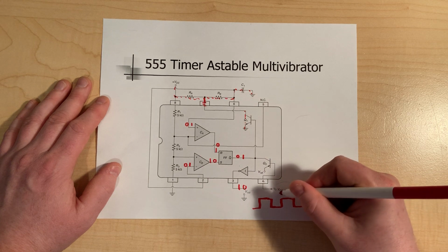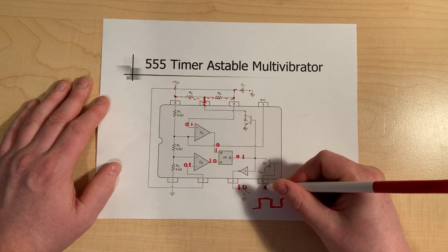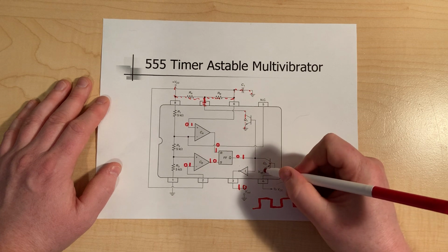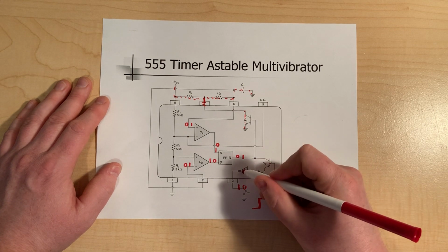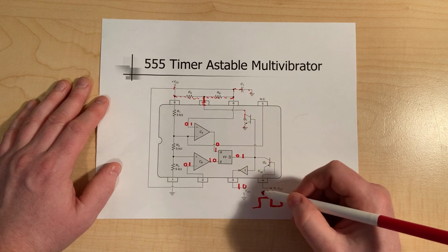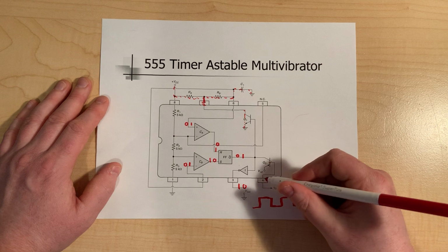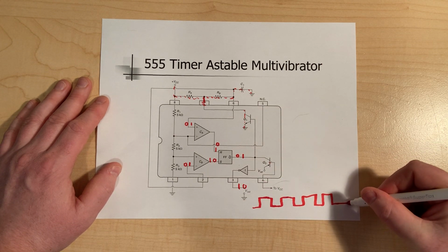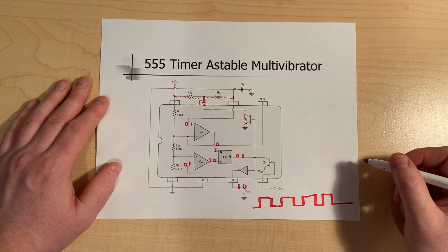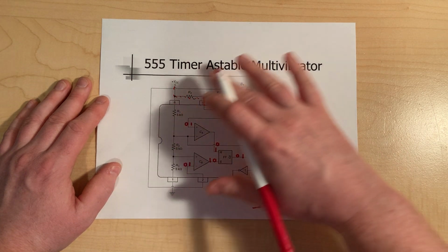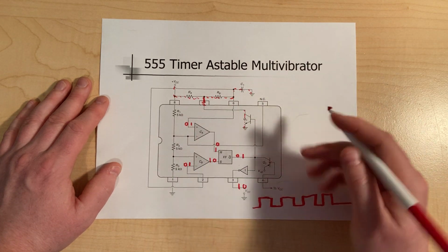If we took the VCC off and tied that to ground, we'd activate this Q2, which would then set the reference voltage here, forcing the output low. Basically this disables the output to force it low. So if you put pin 4 to low, your output would start to just get stuck low. Okay? And for all intents and purposes, that's how it works as an oscillator.